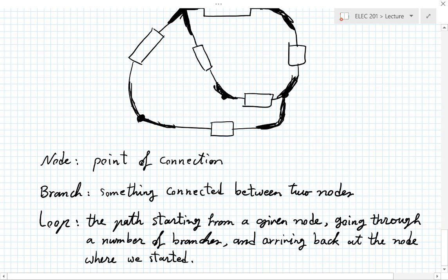And if the element has 3 wires going into it, each of those could have a different current. So you also need 3 currents to describe it. So whereas a 2-terminal element like what we've seen here can be described with 1 voltage and 1 current, a 3-terminal element will have to be specified by 3 voltages and 3 currents.